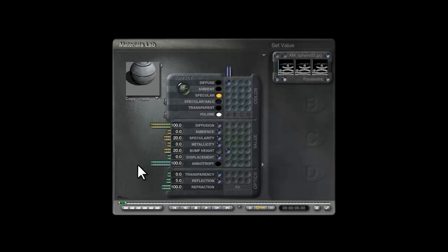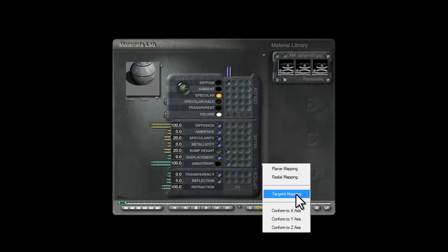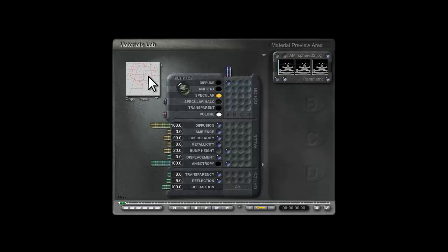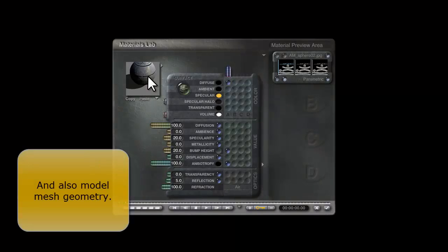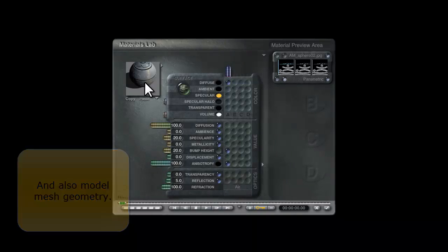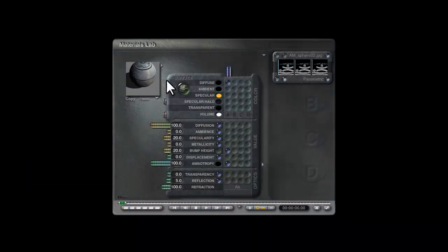We can use the anisotropic effect, and we can actually place the anisotropy under the control of the colour channel here, and then if we use this option to do tangent mapping, it'll change the way that it's mapped onto the surface, so it responds to both the bump output and the colour channel. So that'll create a nice anisotropic specular highlight that will improve its appearance as appearing to be a metal. So that's just a nicety we've got there.